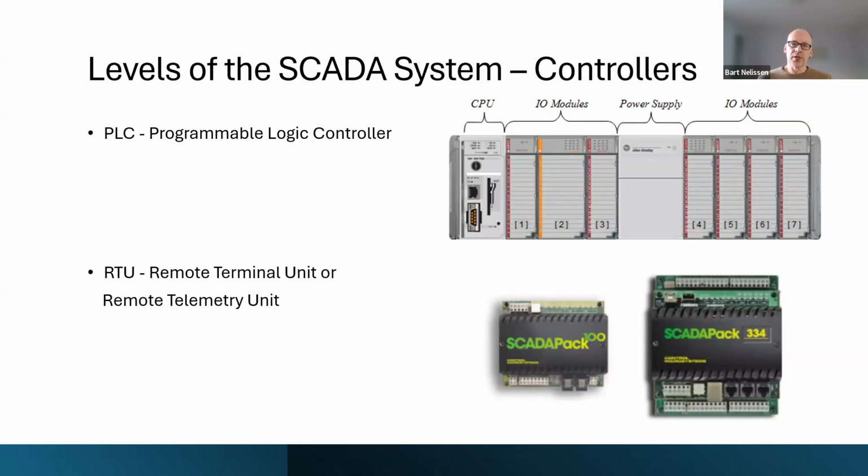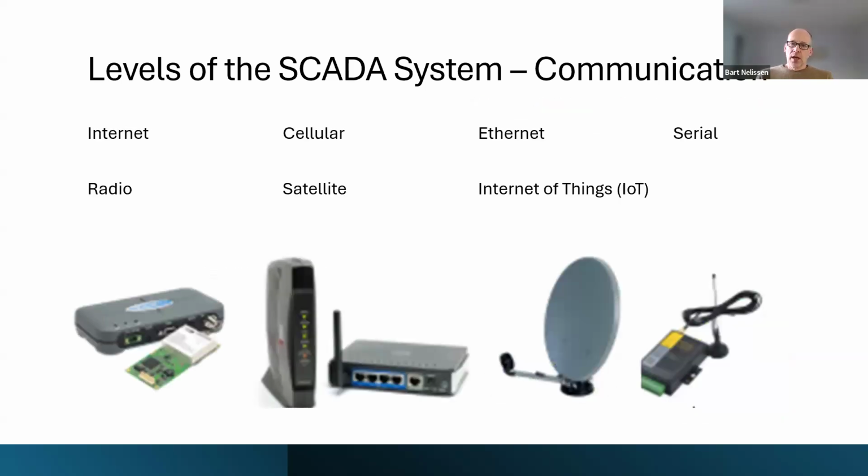So that's that second level, the controllers itself. Once again, the controllers, the PLCs, they will monitor inputs. They then execute their logic within their CPU, and they control outputs. Now, those PLCs are connected through some sort of a communication infrastructure, and that can be a variety. I've listed a couple of examples, but there can be many, many more. And you can mix and match.